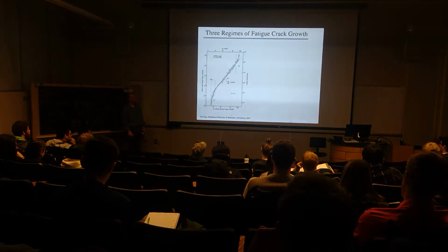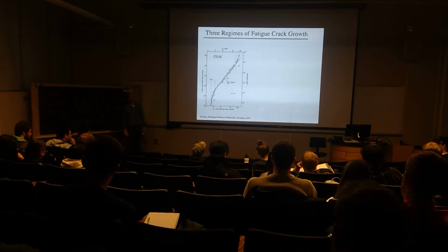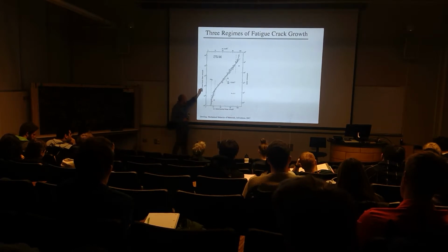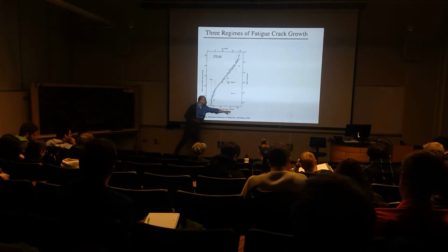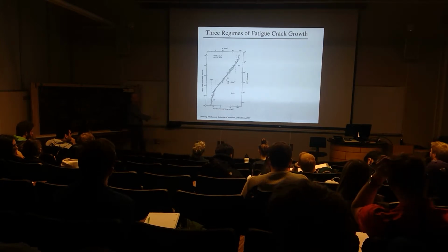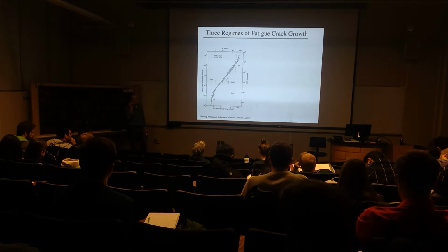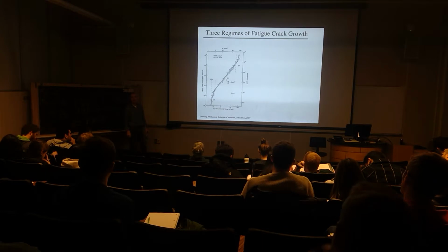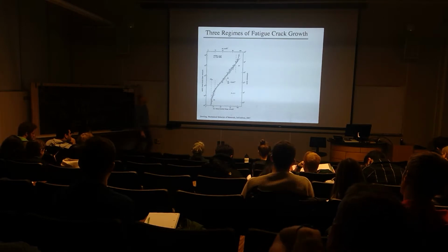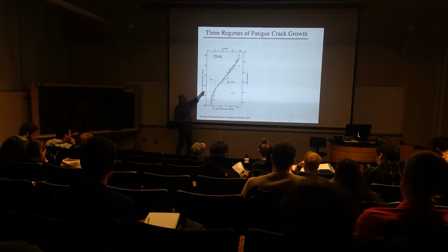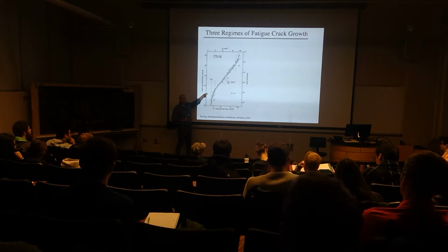Right? And we plot something like this, which is called the fatigue crack growth diagram. Here we're plotting dA/dN as a function of delta K for, in this case, a large number of specimens. Each one of these data points represents the result of an increment of crack growth over a certain span of cyclic loading. So what's plotted is the average stress intensity range for that incremental growth, and then of course the average delta A, delta N that was obtained for that incremental crack extension.